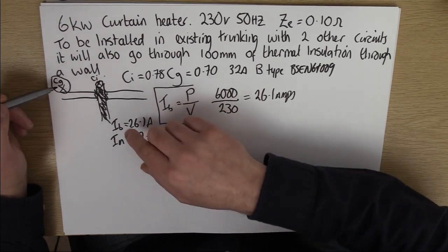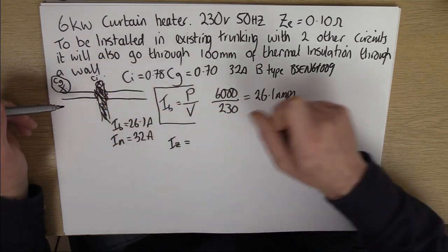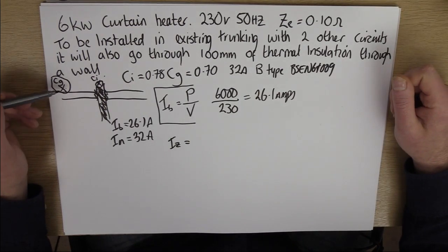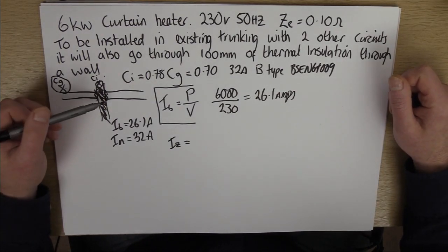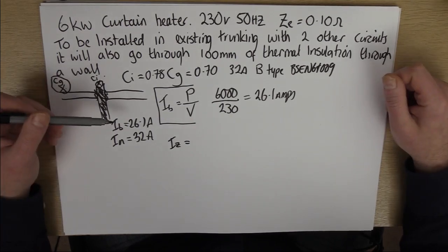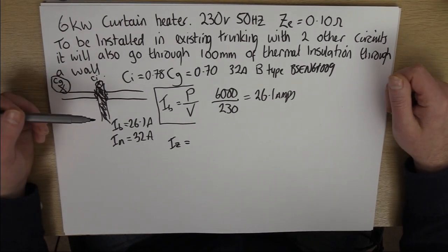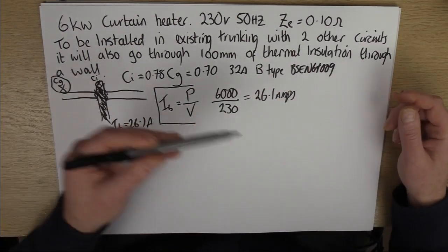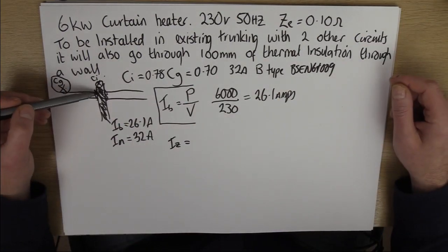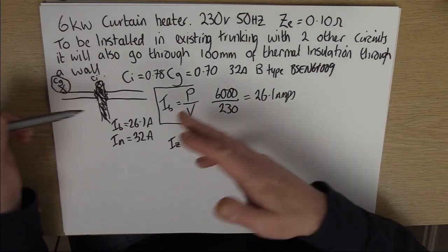So it's only the worst point on the circuit. That's what I'm trying to say. So any factors at the worst point, those are the ones you apply, because that's going to create a bit more resistance. But that would be the same throughout the circuit. The current runs in the circuit the same. So if we calculate for the worst point, then the rest of it will be okay.